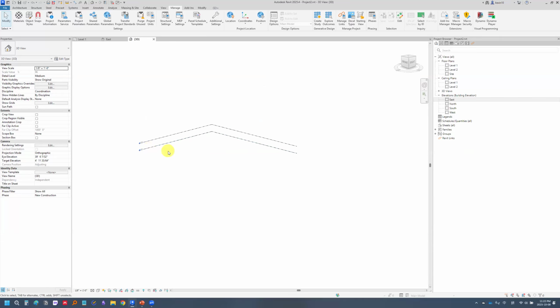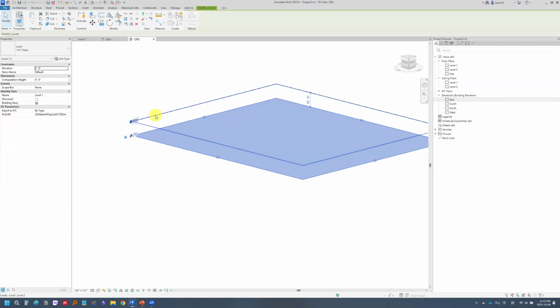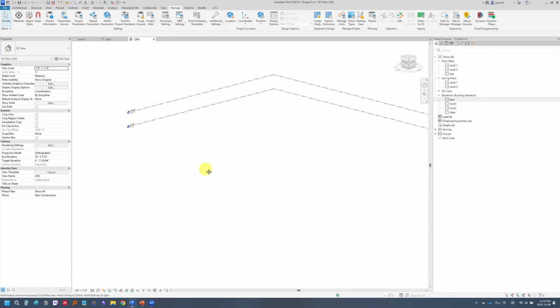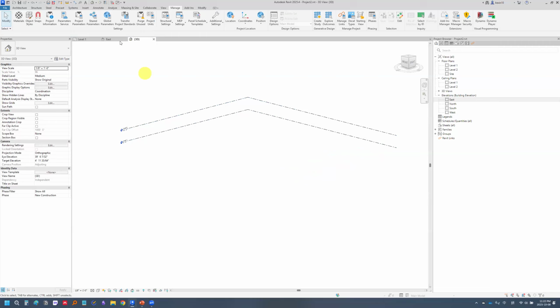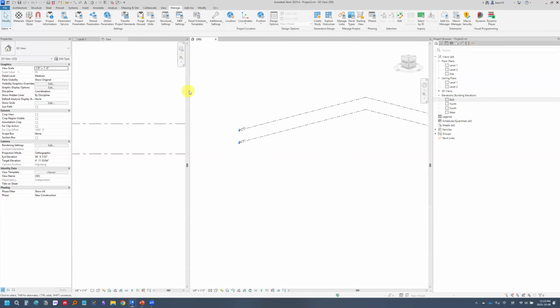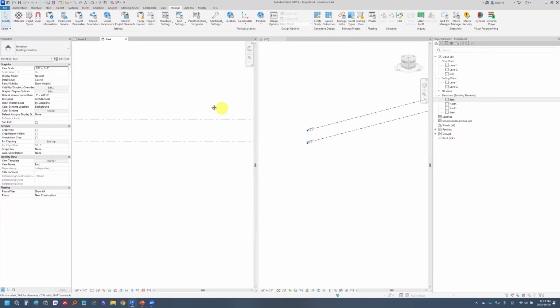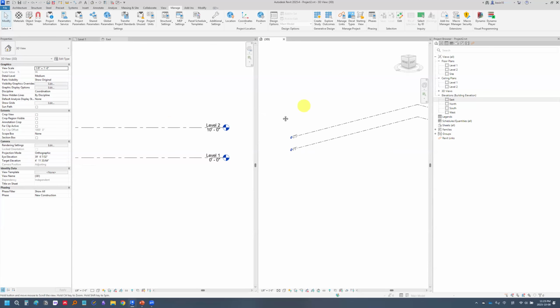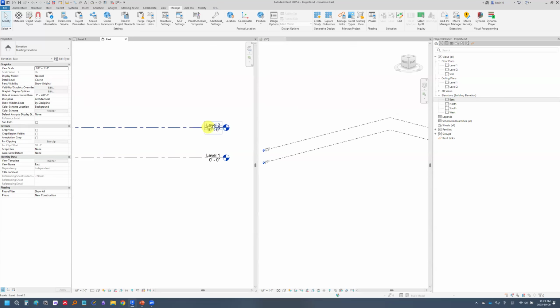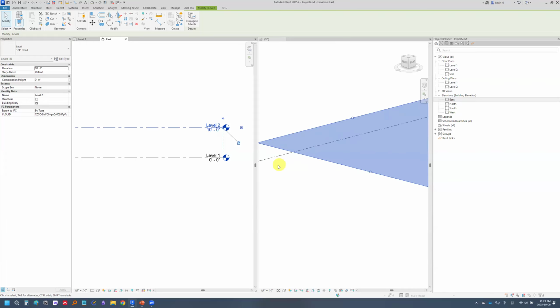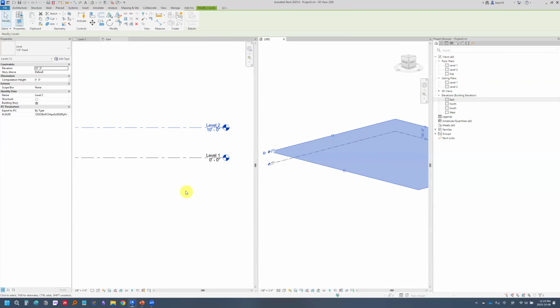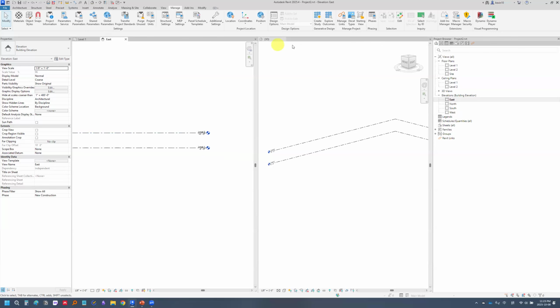Right, so you can see the level defines a plane. This is level 1. This is level 2. And for Revit, the interesting thing is everything is connected. For example, now we are in the east view, the elevation view, and this is a 3D view. If I choose level 2 here, it is also highlighted in the 3D view. So this is the level we have.